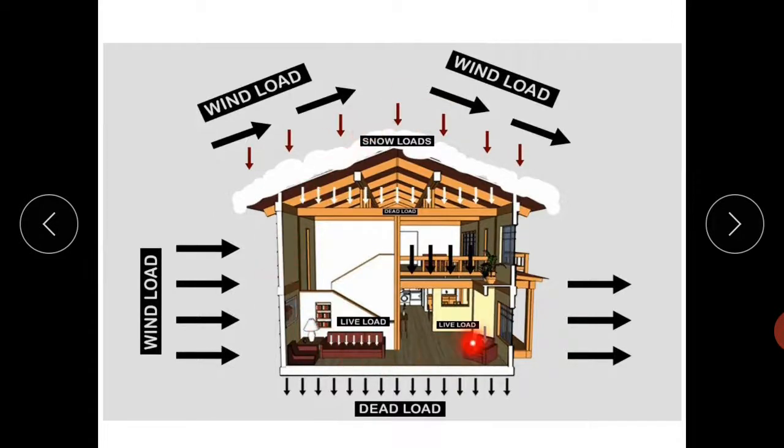So basically, dead load, live load, wind load act on the structure. Dead load is the load which is stationary and not changing its magnitude with time, for example self weight of members. Live load is a moving load which is not stationary, for example vehicle load or students sitting in a classroom. Wind load acts due to the wind pressure.